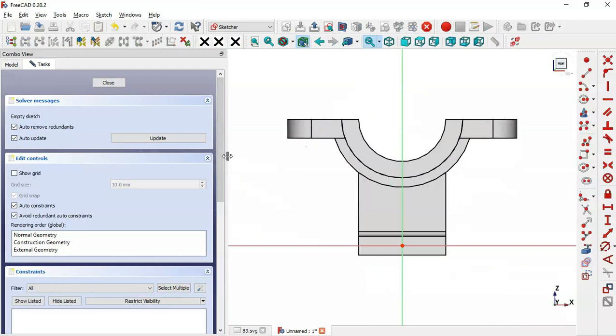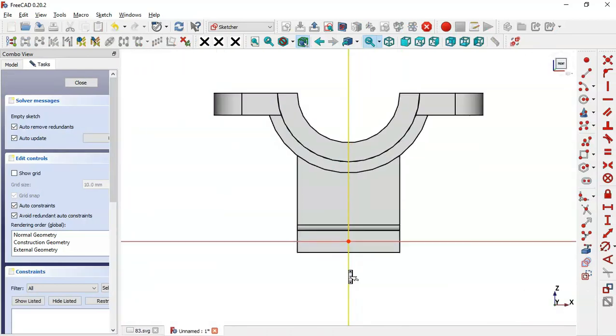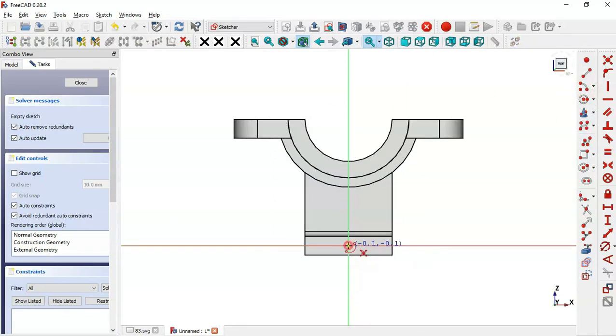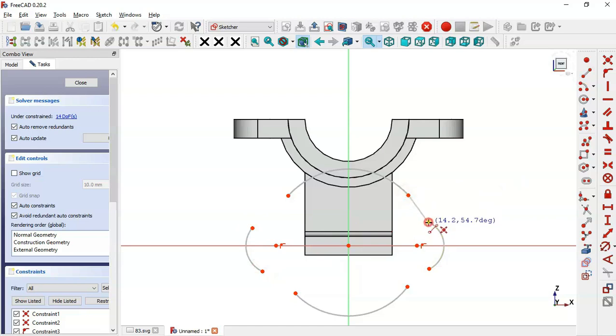Okay, and now resize this window here, and now go to sketch geometries and here select the arc tool, click on this origin point and draw this arc, and now draw this arc here, and next draw this arc in this way, and now this arc, and now select the line tool and connect these points.